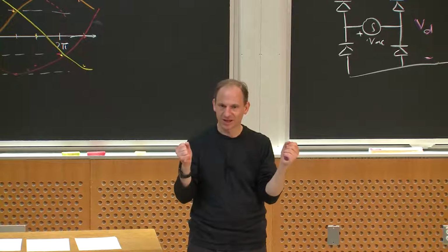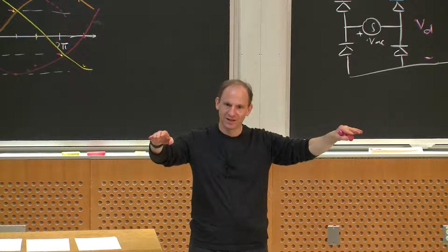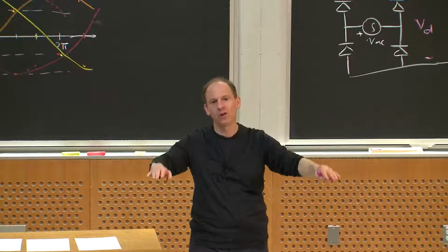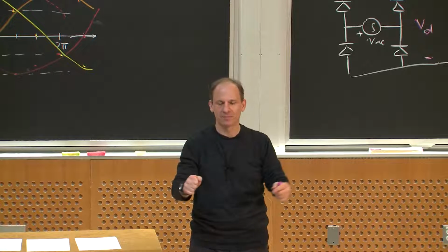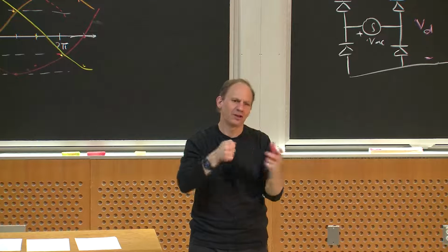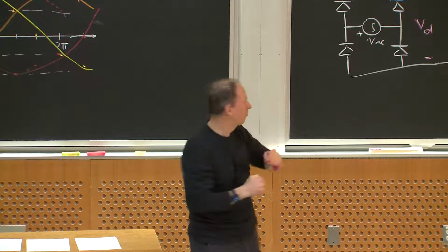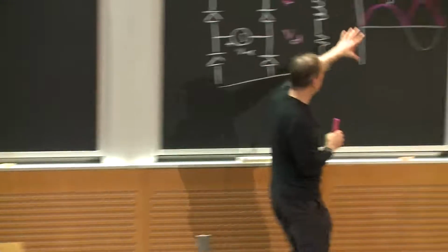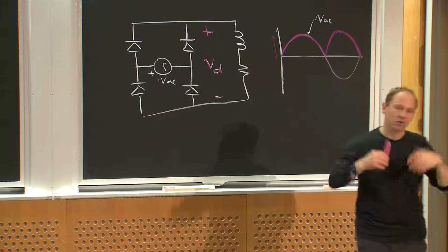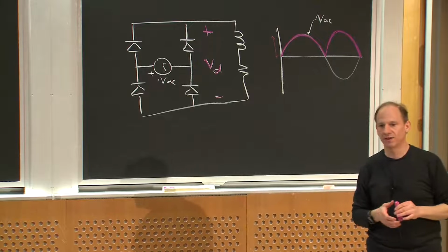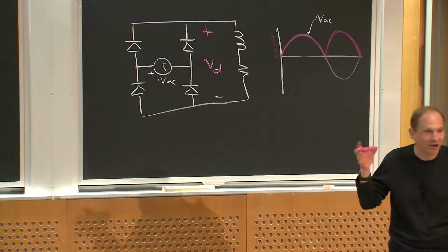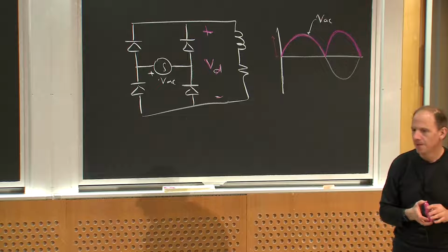You run it into 6 diodes and boom, suddenly you have DC. And they control the amplitude at which they generate by a field control. They use an electromagnet, and they change the strength of the electromagnet, which basically controls how big the AC voltage is. So one application of a three-phase rectifier would just be in your car, every car has one, okay?